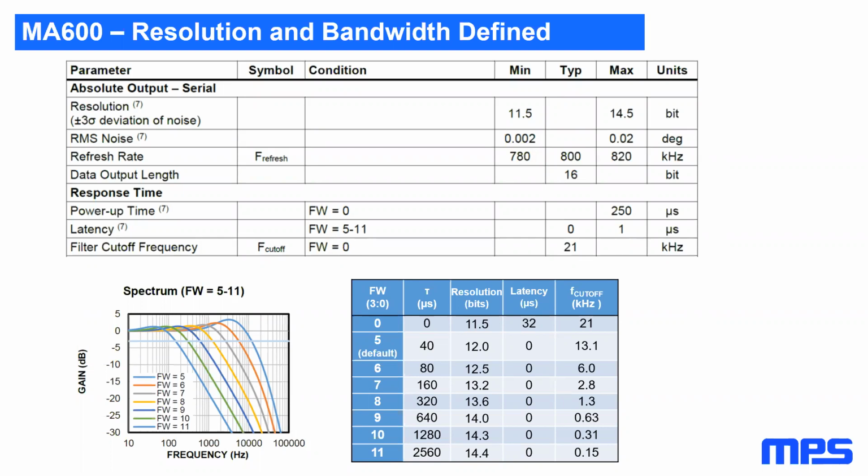What interface between sensor and MCU is best for low latency, and which one is best for higher resolution? SPI. SPI is best for low latency and high resolution. You can run it at 20 megahertz, no problem. We have various outputs, but if you want fast and full resolution, SPI.